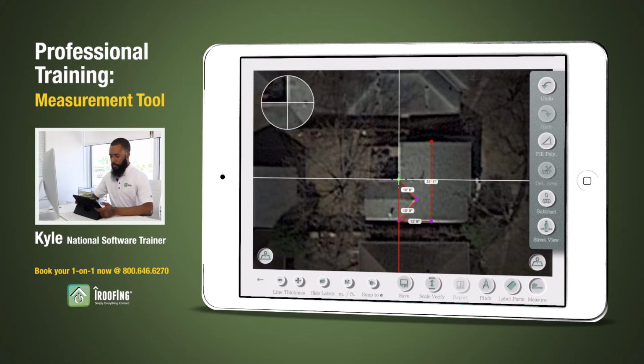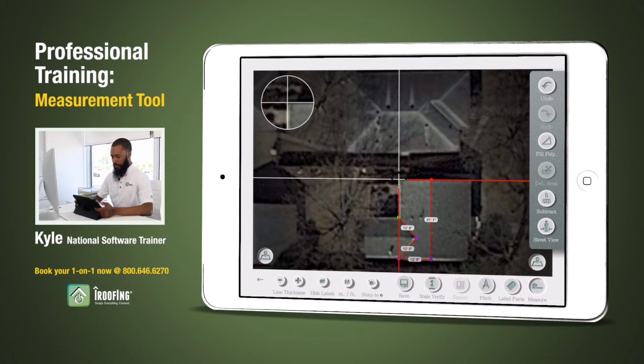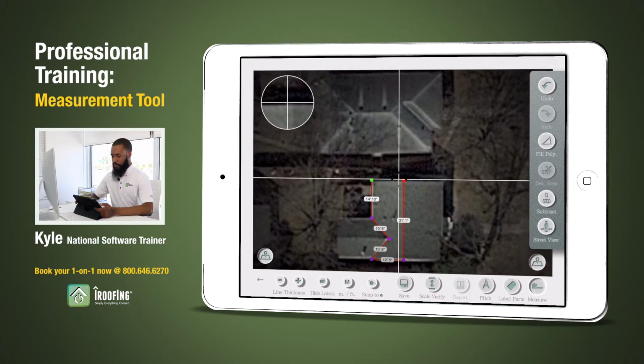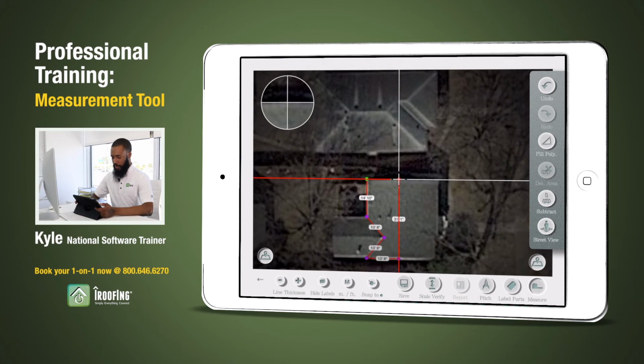And then from here, we're going up this eave until we reach the rake on the opposite corner. Place a marker there. And then finally, we're going over to our right, back to the original dot that we started from. And you'll notice that when you bring your crosshair near that point and let go, it should automatically pull itself into place on top of that dot. The application does that to prevent us from creating an extra dot next to that one instead of using the one that we already have there. Once we hit the marker button on that point, that's going to complete the first area of the roof.